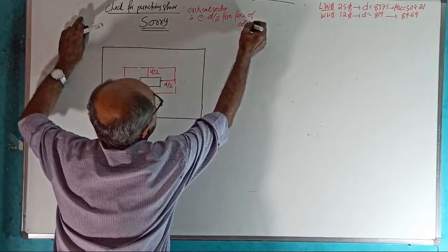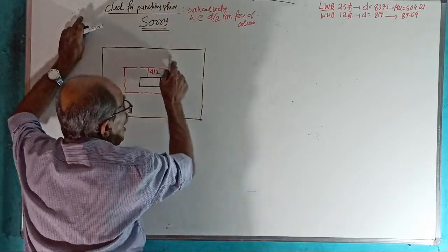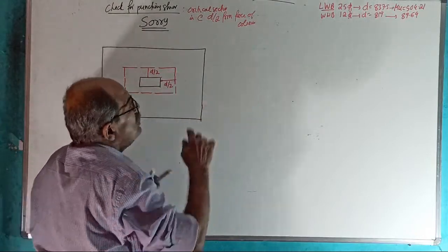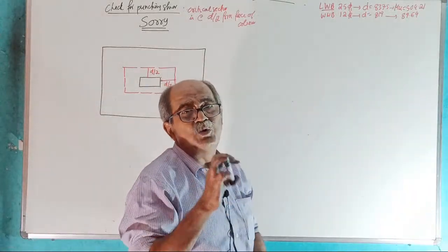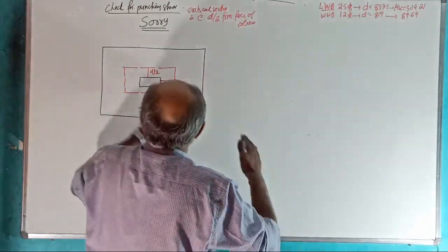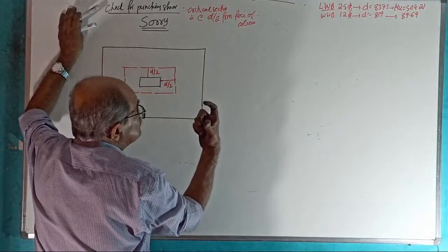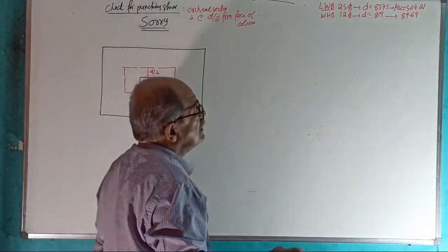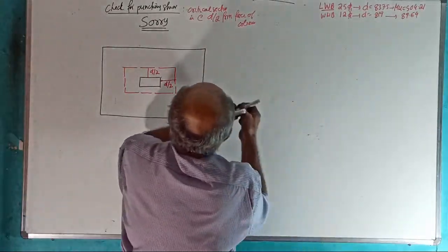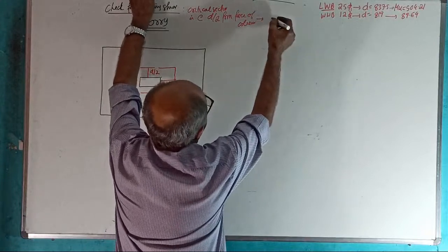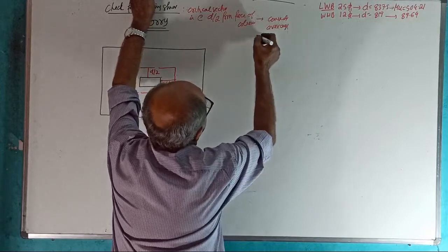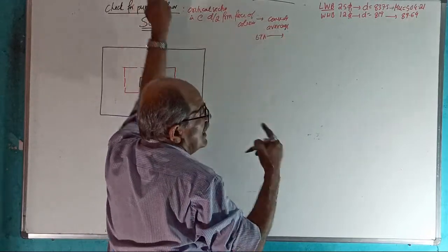Okay. Now there is a problem. Punching shear comes all round. A part of it, see, lengthwise also comes, widthwise also comes. Two different D values are there. Tell what to do. Along one periphery, D is more. Other periphery, D is lesser. Not too much variation, slight variation. So what people take is D, right? Since D's are different, consider average D. See, even your ETABS and SAFE also will consider average D.